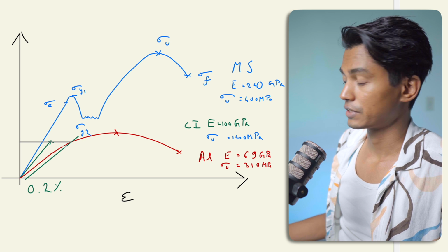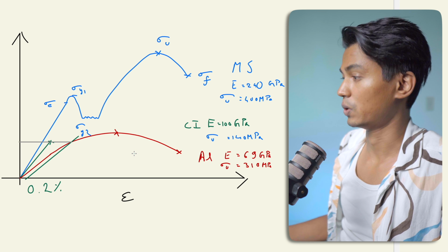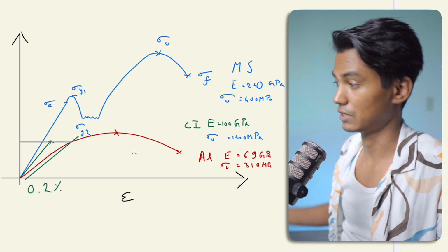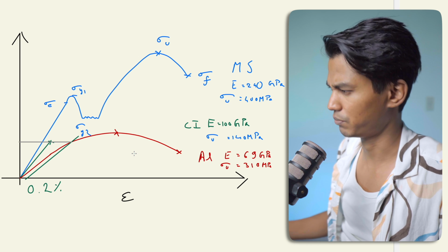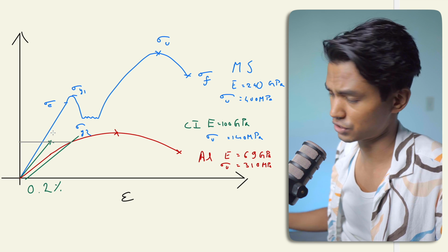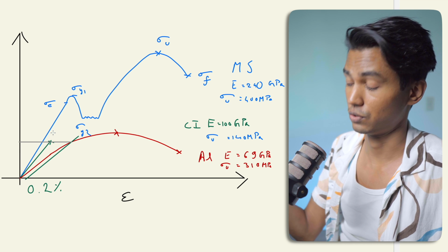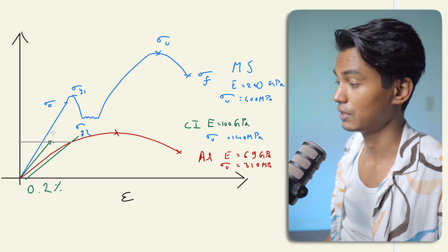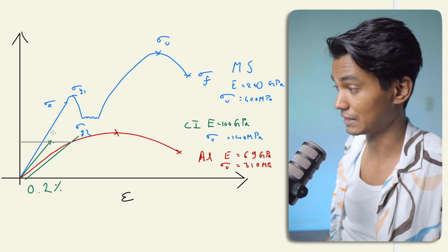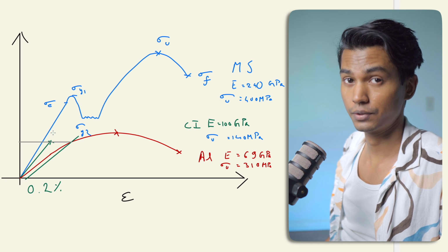So this is a common question: how are you going to find out the yield point? Yield point is also important because that is essentially the point past which plastic deformation starts to happen. Over here you don't even see any clear demarcation or proportionality limit. So the yield point is very important for a material which shows such a bogus stress-strain curve as aluminium. I don't think I will be able to explain why the mild steel stress-strain curve behaves the way it does, but I think we can carry it over to the next one.